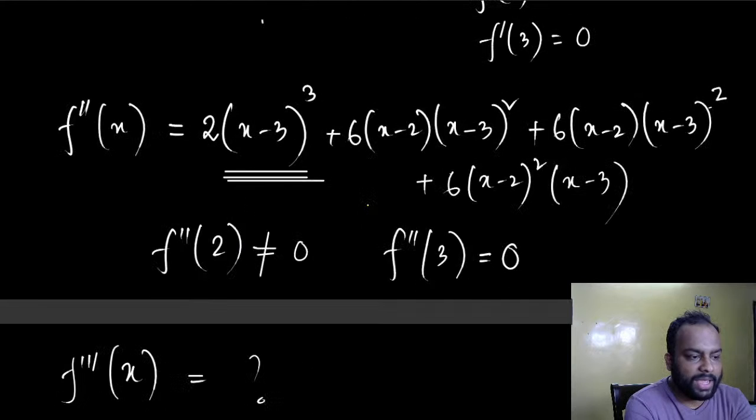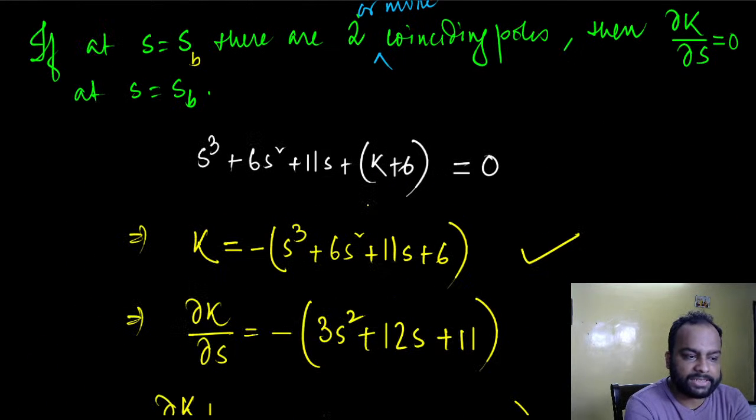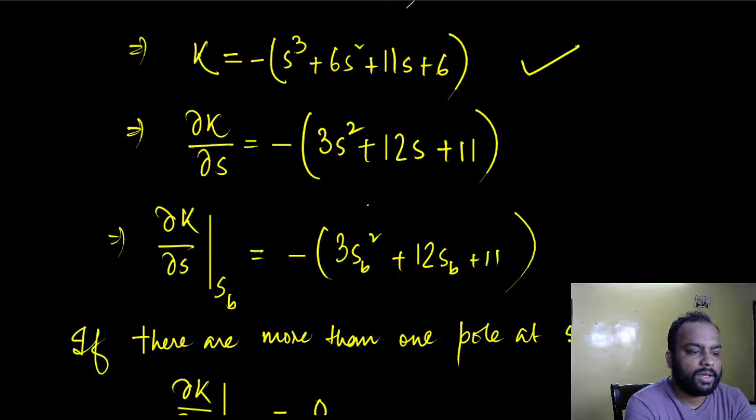So that way we essentially differentiate the characteristic polynomial with respect to s, and once we do that, we make it equal to 0 and solve for it, and the points we get are the points at which double roots or triple roots or quadruple roots could happen, right? So essentially those are the breakaway and break-in points.